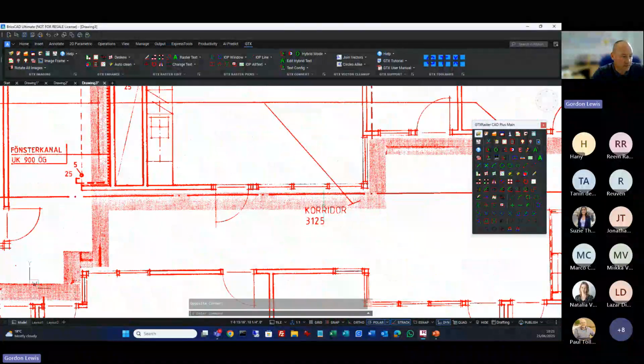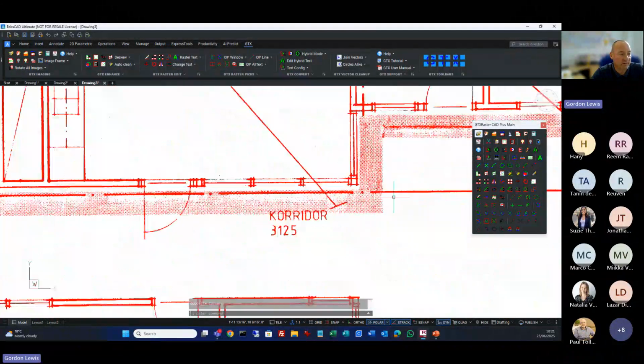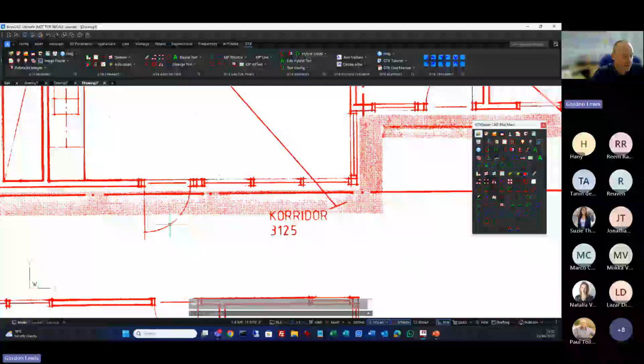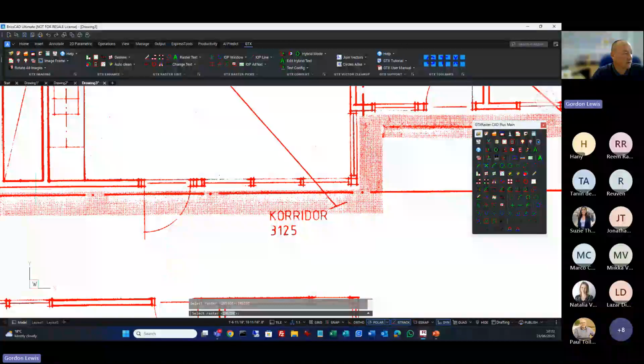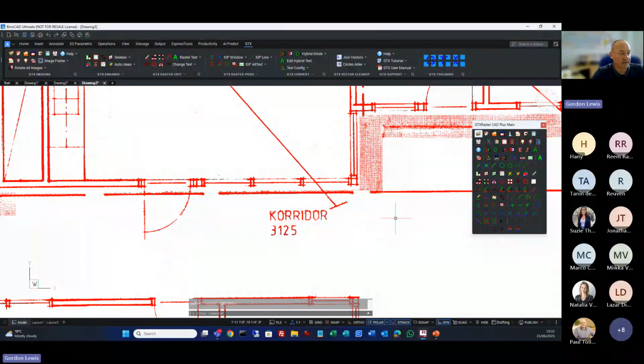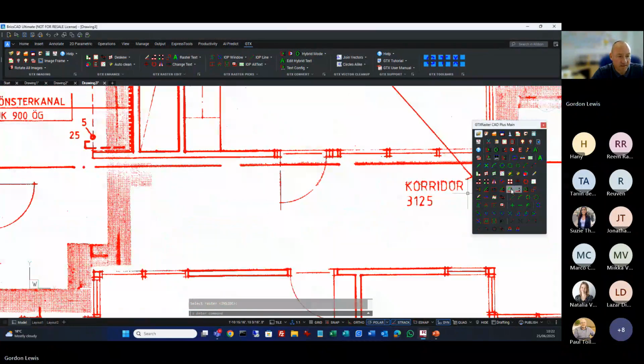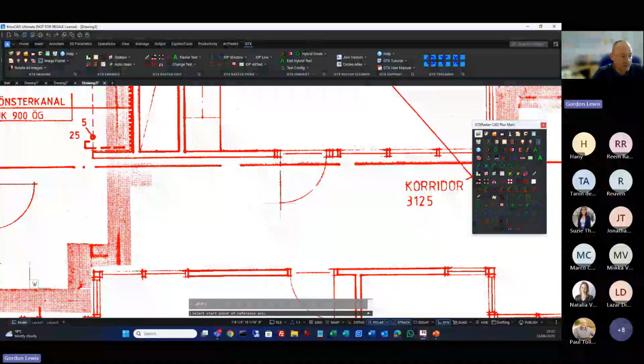But what I want to do is I want to repair some things before I convert. Like this arc is broken. This line's broken. So what I can do is I can get rid of the speckles by saying erase inside, draw a box around it, get rid of that. I can say change the arc.